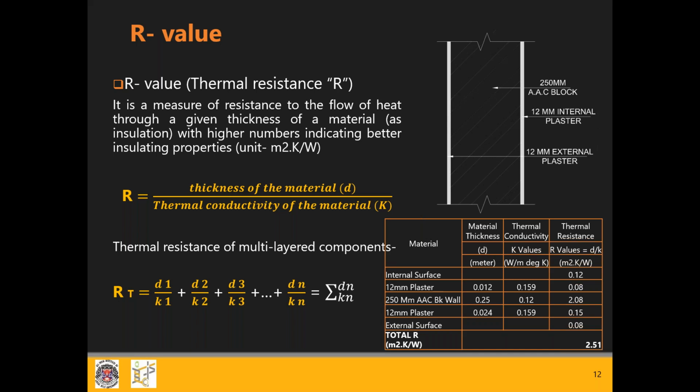One of the mandatory requirements is that you need to test the U value of your material, whether it be insulation, bricks, or AAC blocks, through a third party independent lab according to a specific standard. That standard is ISO. We'll come to that later.